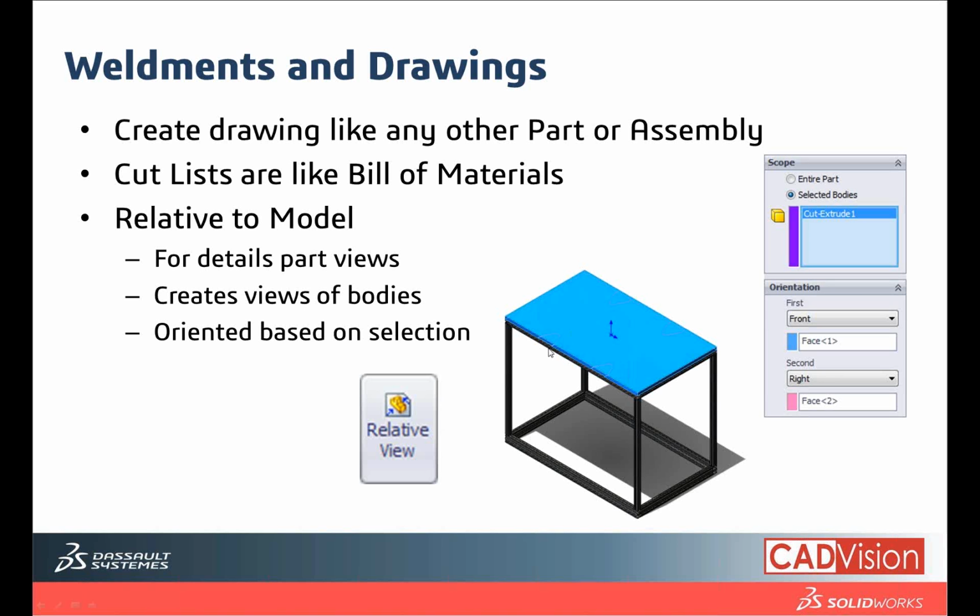Click on that particular part, and you will have these selection properties on your left hand side. It will ask you to select two planes. In my case, I will select the front plane or maybe the top plane for this body face, and use the bottom plane for this plate.